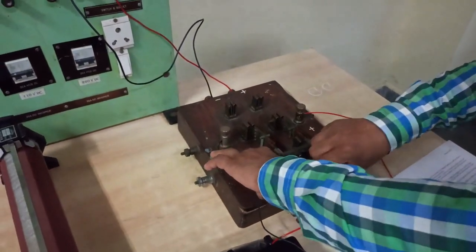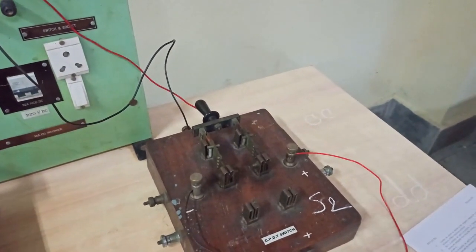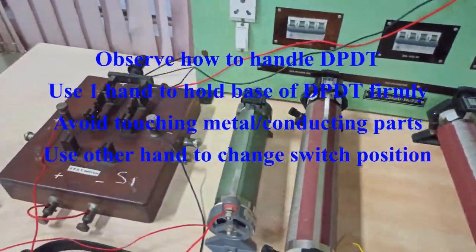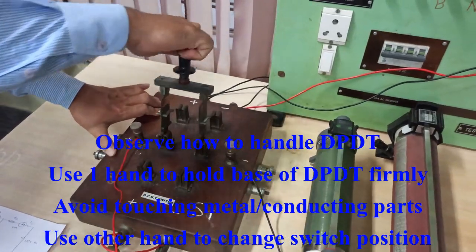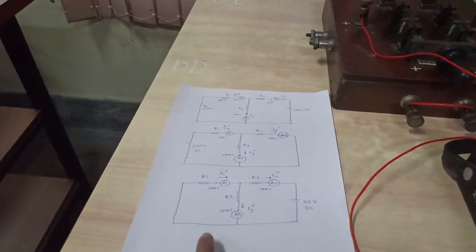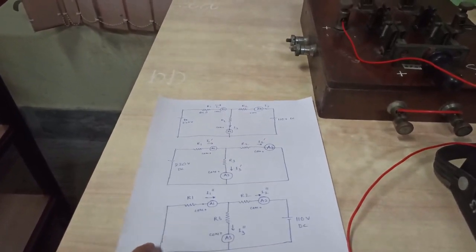So, now we are going to step 3, where we are bringing in that 110 volt supply again. This position, as you can see, has been shifted to the CC side, and 110 volt supply is now given to the circuit, and on the DPDT 1, instead of applying 220 volt, we will be applying a short. So, the 220 volt we are replacing by a short circuit as per this basic diagram, as you can see in this third diagram. Right now only 110 volt supply is there in the circuit, and 220 volt supply is removed, and instead of that we have connected a short circuit.